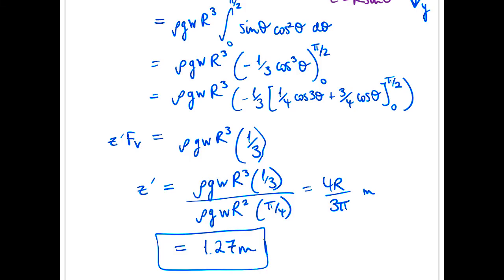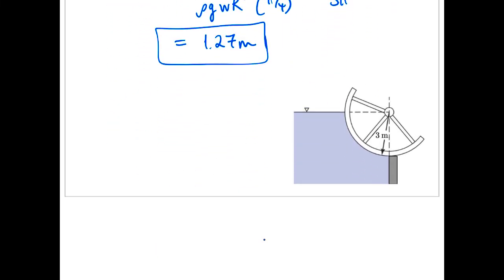So I'm going to scroll down here to the figure, and we figured out the direction of our vertical force from the thought exercise above, and now we have 1.27 meters in the z direction. So I'll redraw the coordinates first. It's really important you get your coordinates right and understand these, because that's another big issue we see in exams where people will solve for a y and an x and not really understand where the reference point is or what exactly this distance means.